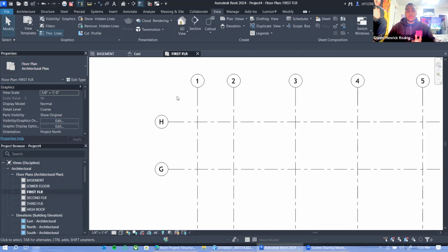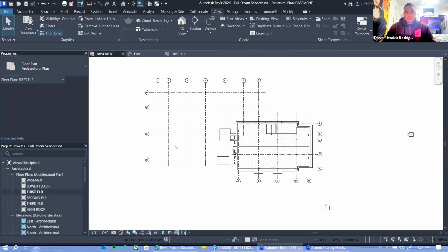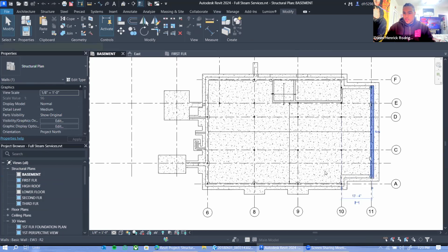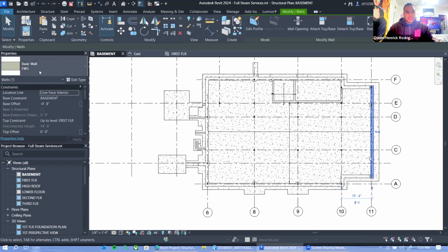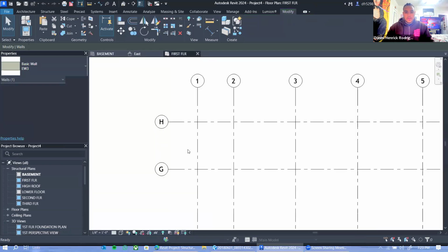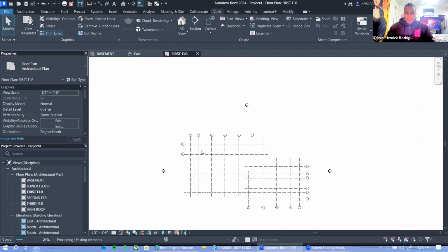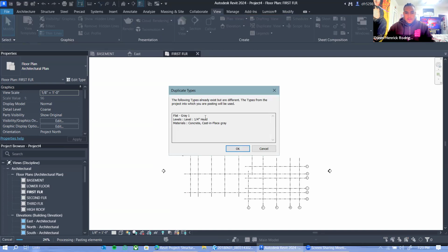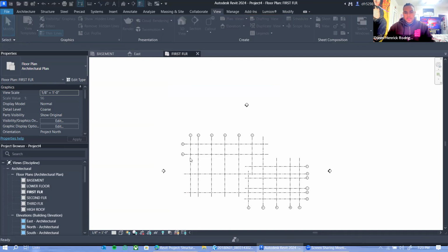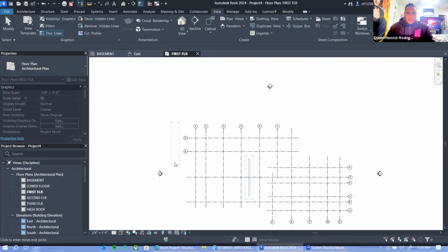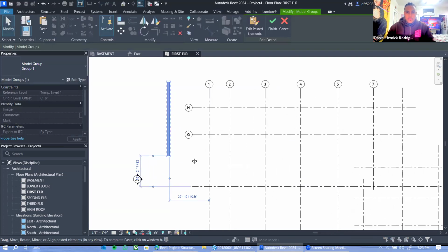What you guys can also do is reutilize some components so that you don't have to recreate them. In this case, I'm gonna go to your old drawing and take a wall. This is the EW3 wall that we had. I'm just gonna hit Control C, go back to our first floor, hit Control V. It's gonna bring all of those materials and the assembly back into it. I'm just gonna paste it, and then you can see that wall right there.